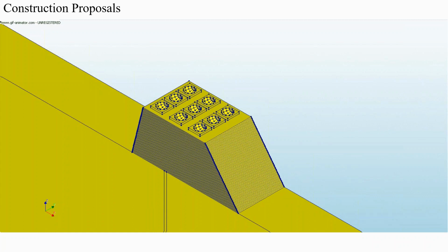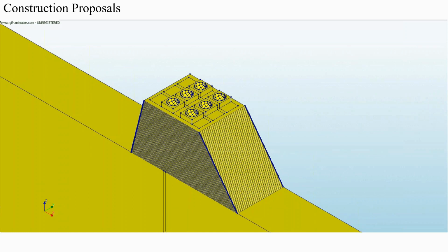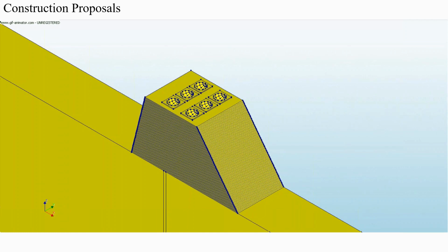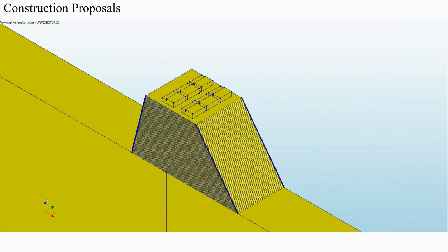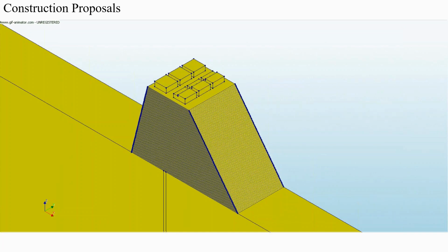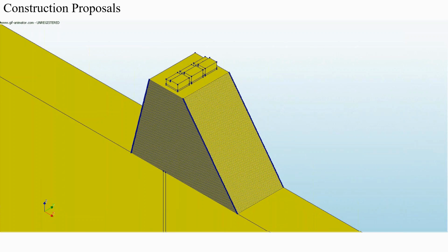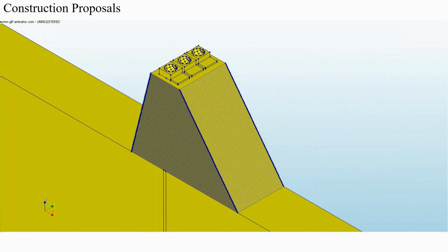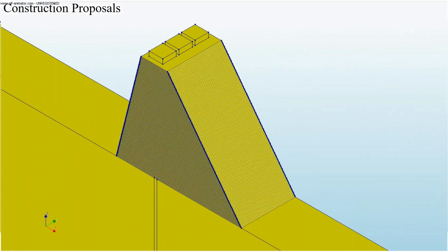Shear connectors should be considered on the outer face of the boxes for increasing the friction surface and ensuring enough bonding between precast concrete and cast-in-situ roller compacted concrete. However, placing drainage pipes connecting the boxes is a complicated issue for this construction. So the use of low permeable concrete in the precast boxes will minimize the probability of filling the bubble with water. However, it will prevent water from going inside the bubble.